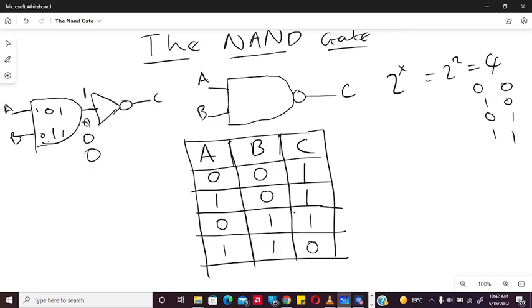And again, let me repeat this. If you forget how the NAND gate is working and its truth table, don't worry and don't stress. Just break it down into its simpler components and work it out from there. You can actually form a general rule from this truth table. Check out. Every time there's 0 0 or 1 0 or 0 1, or when there are bad terms for the AND gate, that's when the output of the NAND gate will be 1.